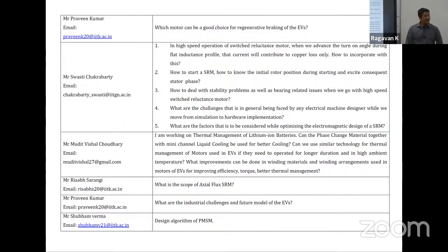Other than that, you can do active compensation. There are some active compensation methods that specifically allow you to lower the vibration you get. But keep in mind, that's not solving the problem. So you can do active torque ripple mitigation or active vibration compensation for systems, just like a Bose does. Basically, you can try to muffle out or clip certain frequencies.